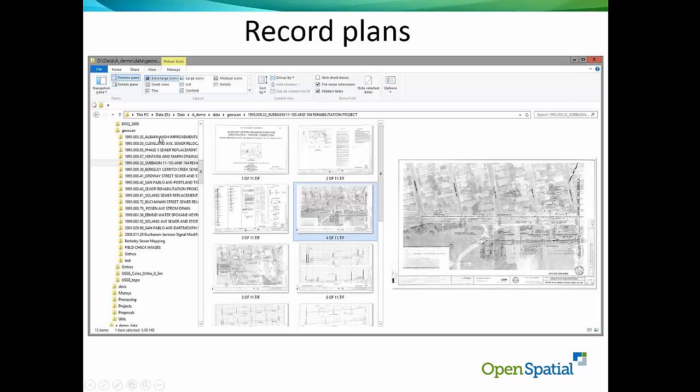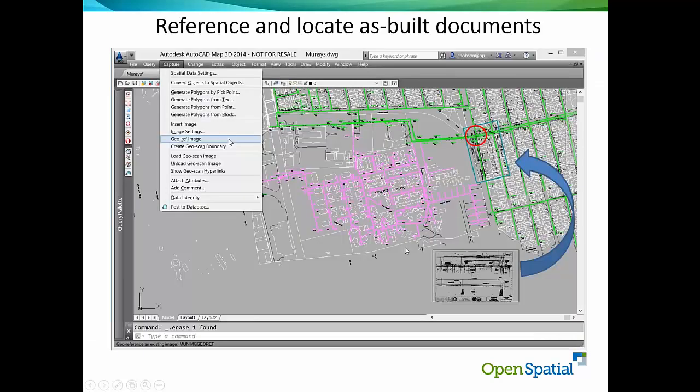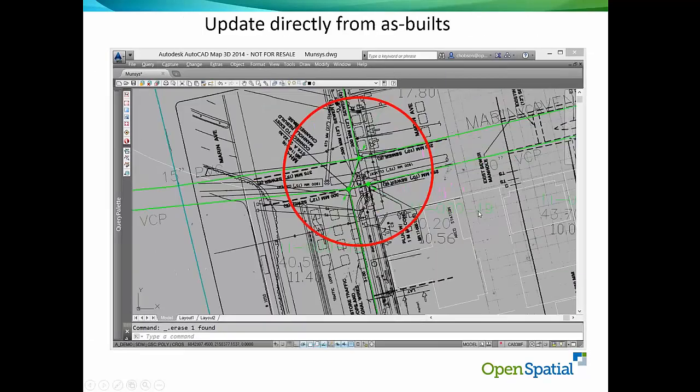Hopefully nowadays people have the actual drawing, but this is still a useful set of CAD data that came in, these plans. And so one of the things we'll do is we can take those plans, throw them in the background, and I'll spare you all of the details. But in essence, this CAD drawing has a lot of data. What I'm going to show you is how to take the CAD drawing and actually get it to be GIS data, and how do we do that?